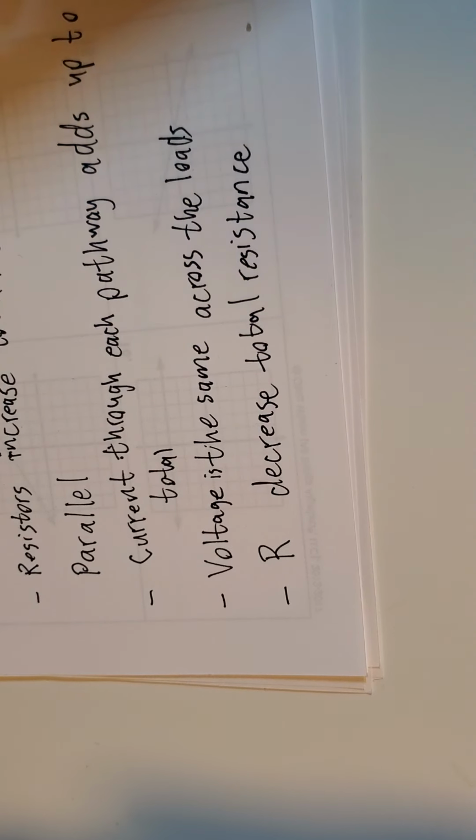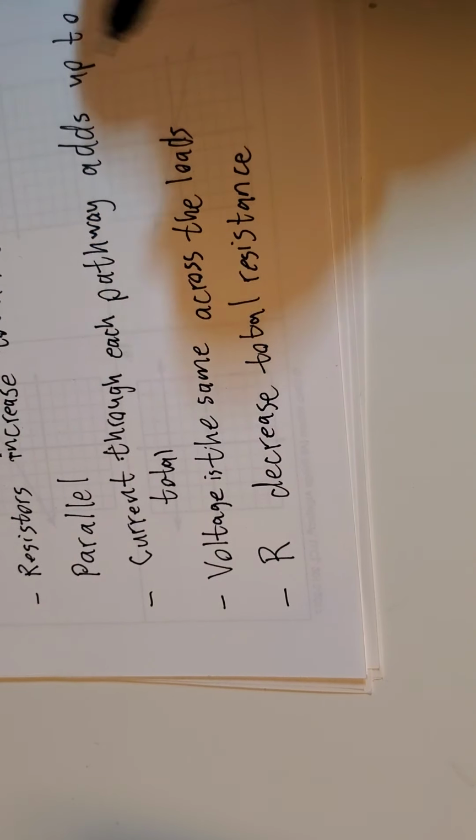But as soon as you give that second option, despite it maybe having a little bit of resistance on it as well, now your current or your electrons are going to get to pick which way they want to go, and they're going to pick the easiest way. So it ends up being overall lower in resistance. So as you put things in parallel, your resistance is going to be going a little bit lower, and so your current will actually go up, right? Because there's less resistance to your flow.